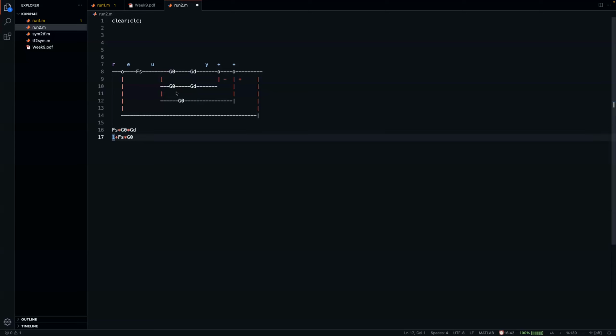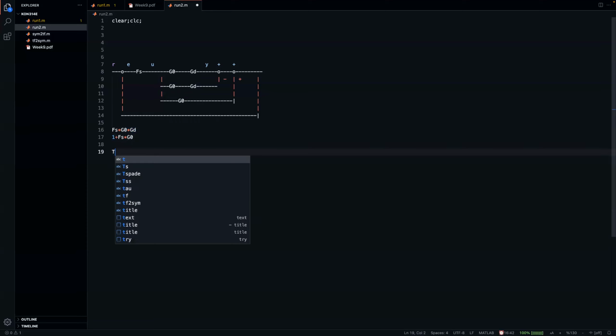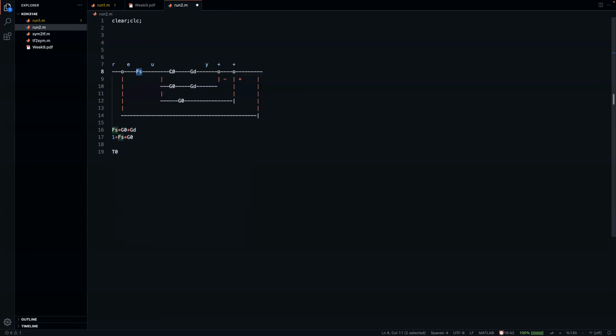You have to do the eliminations and the calculations, and you will end up in this closed loop here, which is interesting because this GD is pure delay in our case, and Fs times G0 divided by 1 plus Fs times G0 is basically T0. T0 being the controller and the non-delay part and the closed loop of that, because it is directly the formula that we would use if we would have a controller that is directly applied to the non-delay part.